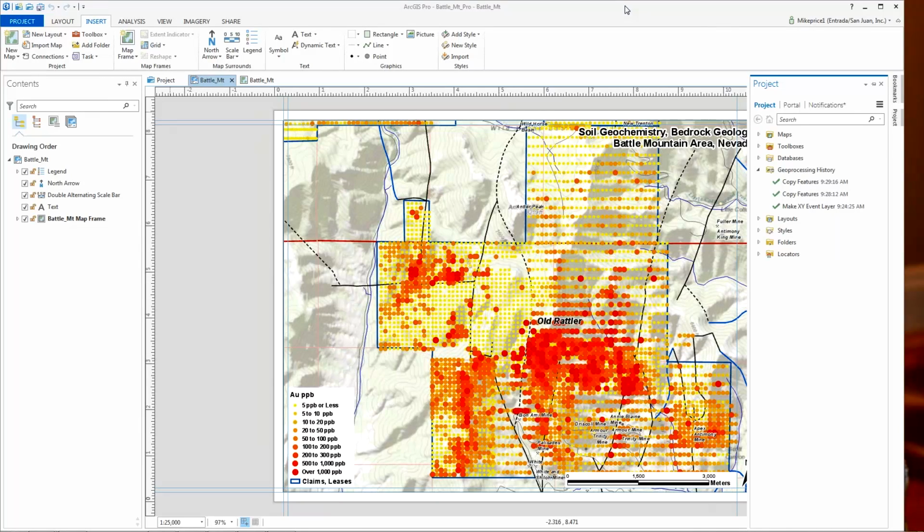In fact, you brought up a good point, because when I save this as a training set, I'll probably save it back down to 10.3 so that we have the original earlier version geodatabase available. There are problems when you're running an earlier version of ArcMap and you try to open a 10.5 geodatabase. You will hit the wall. It won't work.